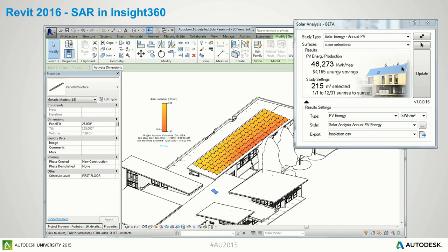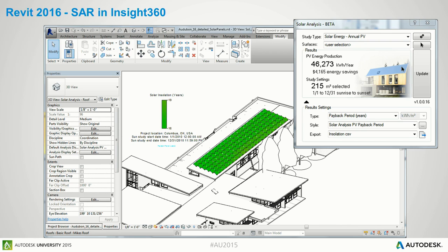Typically people say latitude tilt is the ideal for PV panels, but it's not always the case because of seasonal cloudiness and things like that. It usually turns out to be slightly different than latitude tilt. You'll be able to see that here because it runs every hour of the year with clouds and everything in mind. So then I'm just cycling through my other metrics for performance.